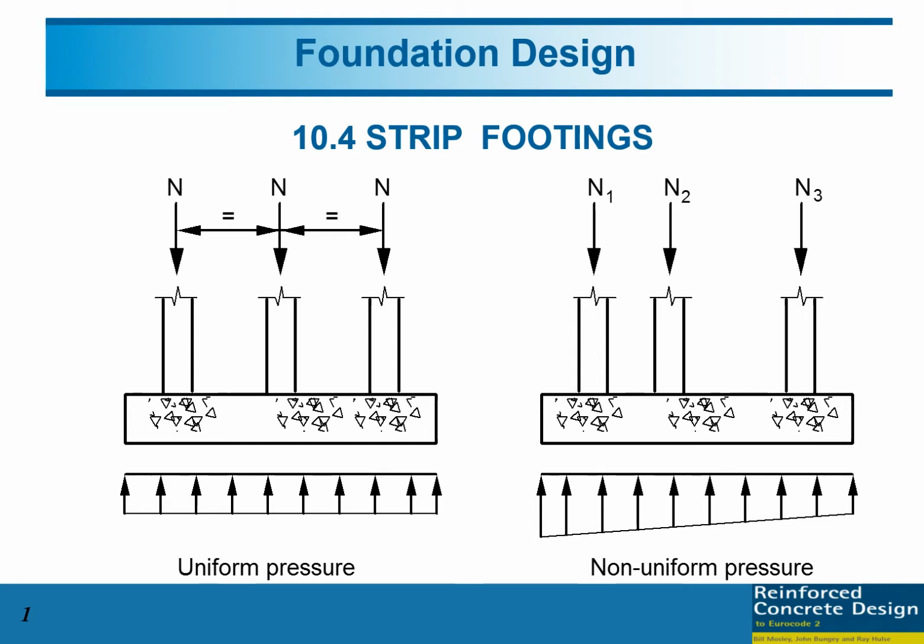So actually why do we need to provide the strip footing? So we start with the pad footing. Okay, so when you design the pad footing, and then after you do the design for some of the footings, you find that two footings need to be combined because they have overlapping of the pad footing, so you can design them as a combined footing. Okay, so now you have too many combined footings, and between the combined footings there is also overlap, so you can convert these combined footings into the strip footing, in order to reduce and make uniform the pressure from the soil.